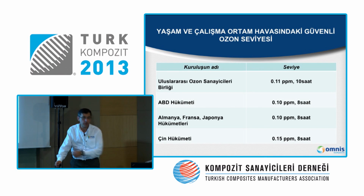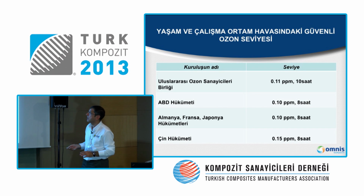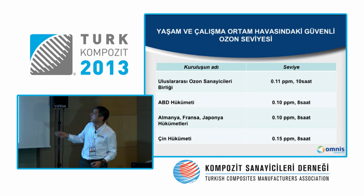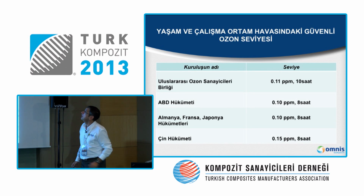So that's important. For ozone and every chemical, of course, we have certain levels. The World International Ozone Industrialists Union says that the level of ozone can be 0.11 ppm for 10 hours. The United States has 0.10 ppm for 8 hours. Germany, France, and Japan are at 0.10 ppm for 8 hours. And China gives an allowance of 0.15 ppm for 8 hours.